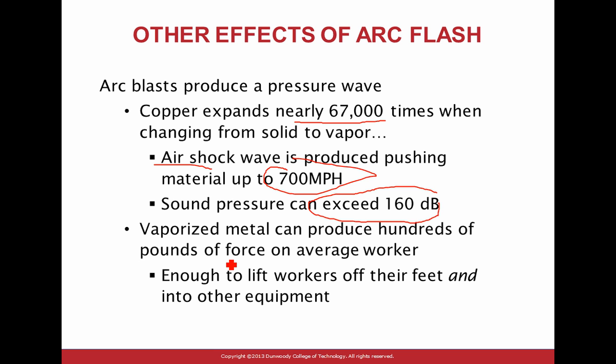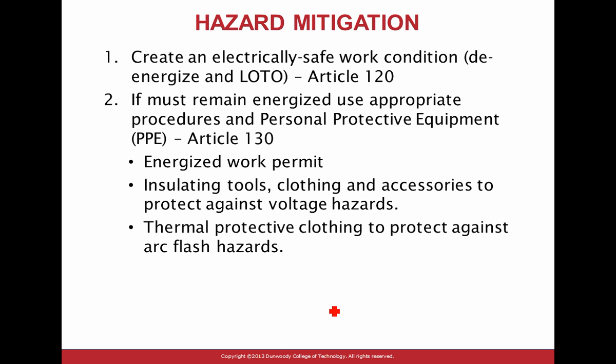You will survive the fire. You're not going to die from the fire and the arc flash, but the energy, the pressure wave that's going to push you off your feet and throw you against the wall, will kill you if you go higher than category 4. It's enough to lift a worker off their feet and into the equipment. So after category 4, don't bother to work on energized equipment.